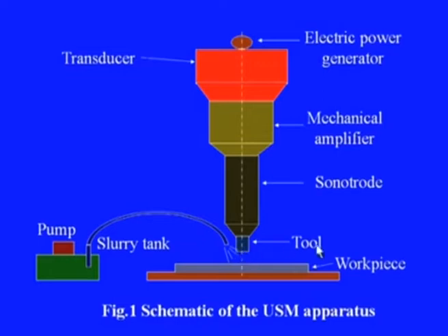That arrangement can also be made in this control system. Coming to the movement of the tool in the USM process. During one strike, the tool moves down from the most upper remote position with a starting speed of 0, then it speeds up to finally reach the maximum speed at the mean position. Then the tool slows down and eventually reaches 0 again at the lowest position.